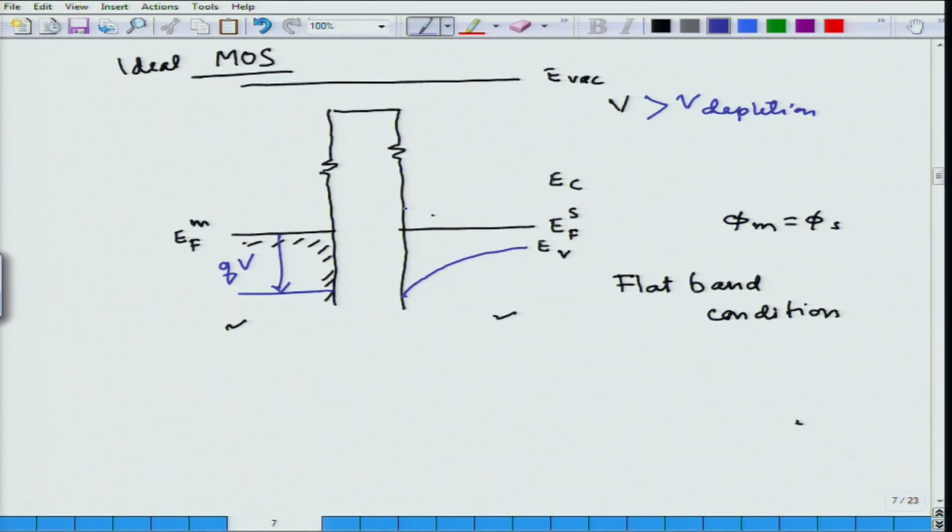be quite extreme. Now, this is a very interesting case, because what is happening here is a material which was p type, Fermi level remains the same, there is no current flowing in the semiconductor, the material on this side is p type, because the Fermi level is below the intrinsic level. On the left side the Fermi level goes up, so the material is actually becoming n type. And this particular region where you apply much higher positive voltage to a p type MOS device is known as inversion. Inversion because it is changing from a p type to an n type device.